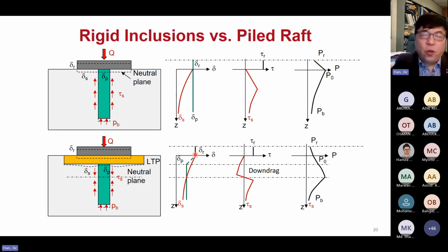So from here, there is cushion compression above the pile. Then the pile will penetrate uniformly, so the soil starts from the top and deforms like this. In this zone, the soil will deform more than the pile, and in the section below, the pile will deform more than the soil. That plane is called the neutral plane.